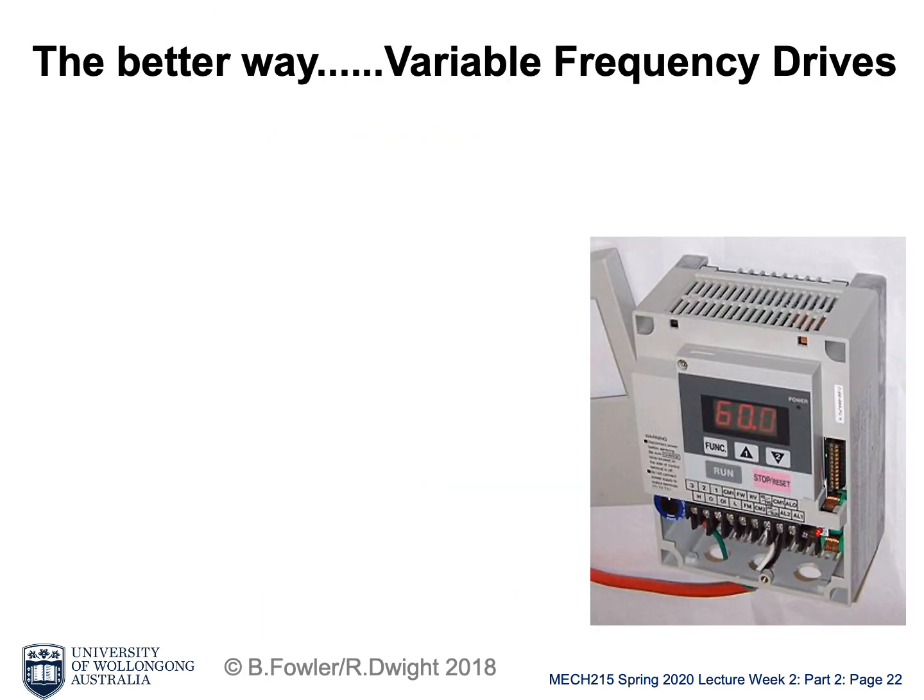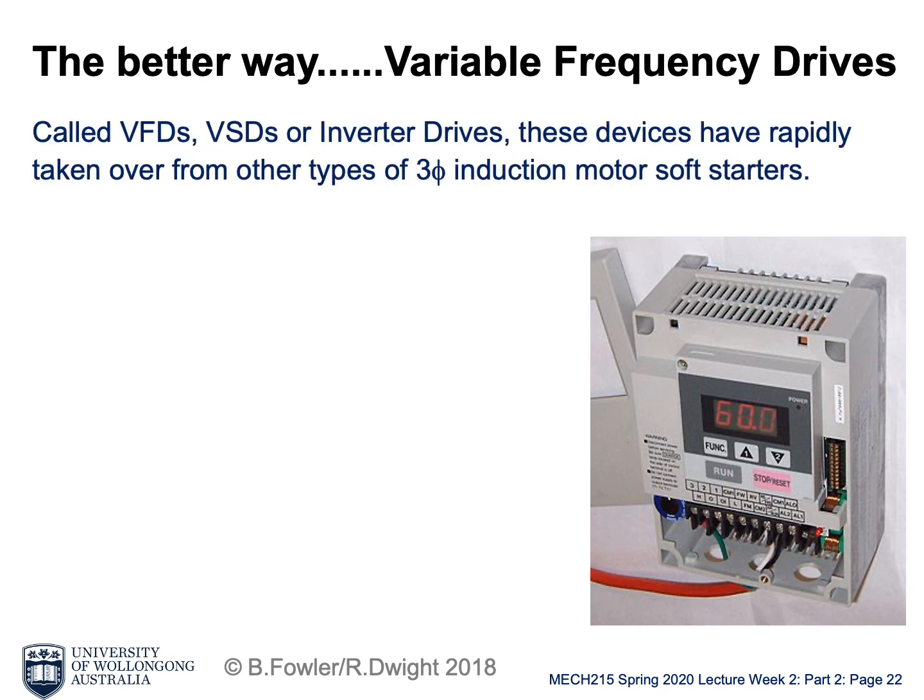The better way is called a variable frequency drive. It's short for VFD, and another name is variable speed drive, VSD. This device is much more complicated than the soft starter we mentioned in the last slide. You can see there are many more terminals on this device, and they connect between the power supply and the motor.